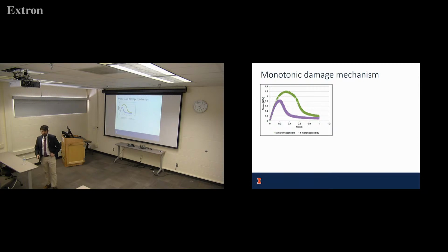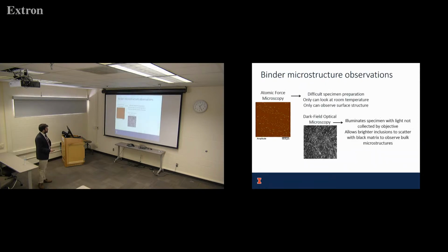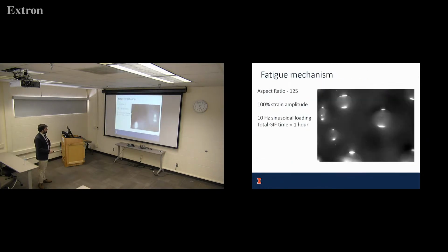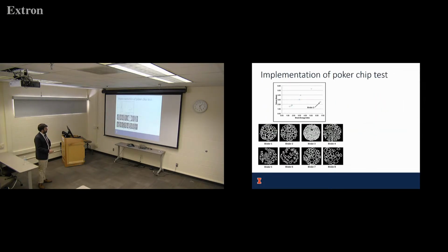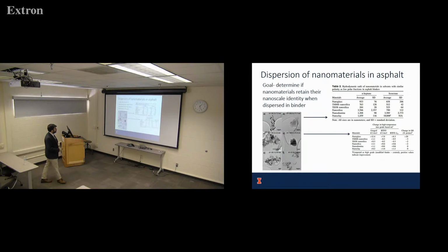So, yeah. On this nanomaterials paper, did you guys use titanium dioxide? We didn't try titanium dioxide. They were all oxides. There was aluminum oxide, trying to think, silica oxide, yeah. And those we called nano silica, nano alumina, nano clay. I don't even know what went into that one. That was a really weird one. And then this nano glass is a proprietary thing developed at UT Brownsville, and they just sent us that material and we're like, try it out. It ended up actually being the best one, like plus 20% elastic recovery. So from a performance perspective, it ended up being the best one.